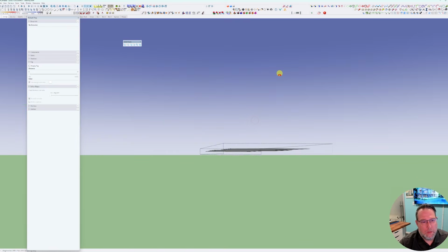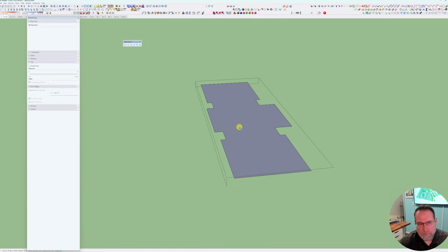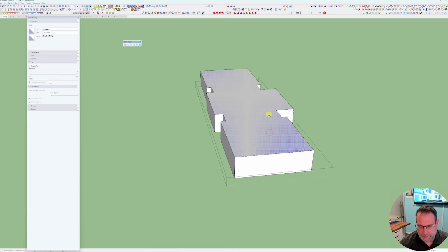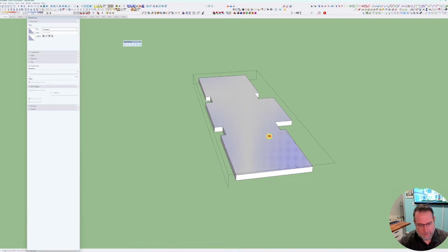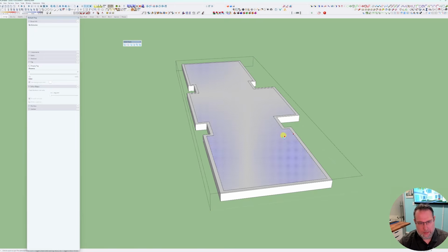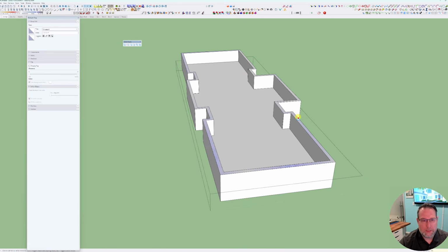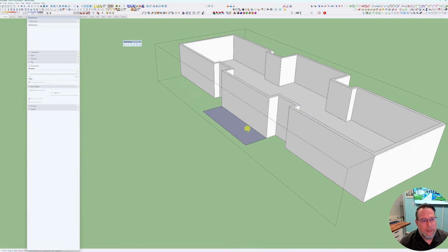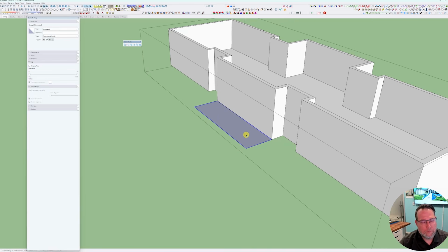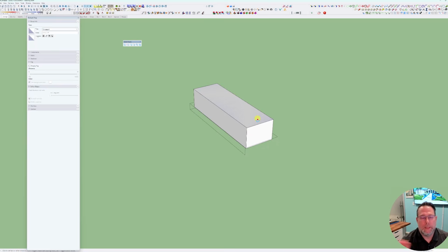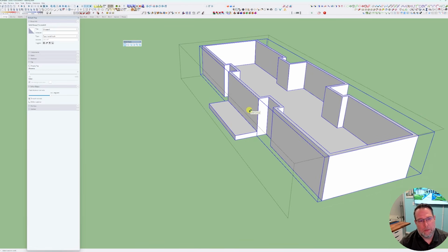So now this time, when I'm interacting with here, we generally use 24 inches for our interstitial space to allow for mechanical and all that sort of stuff, again here in Florida. So I'm going to do 24 inches, do my same 10-inch offset, and maybe we'll just do 10-foot ceilings on the second floor. So I'll raise this up 10 foot too. And then here, this is a balcony. I'm going to double click this. So since I want a 6-inch step, I'm going to raise this up 18 inches because we did the other piece 24 inches.